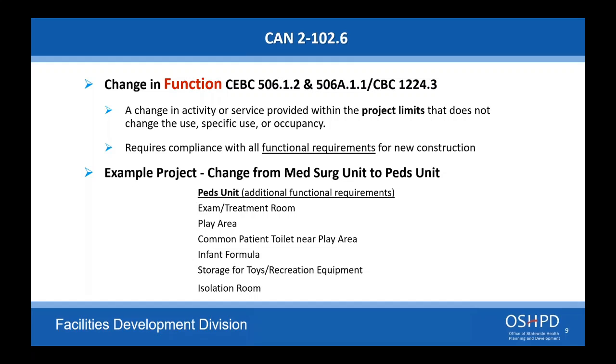Yeah, you can use the ICU rooms as ED bays, but you're gonna have to look at the clearances required for the ED. Again, you have to meet the functional requirements of the new use. So a new emergency department is gonna have clearance requirements for each bed position, for each bay. It's gonna have nurse station requirements. All those things need to be identified and applied.